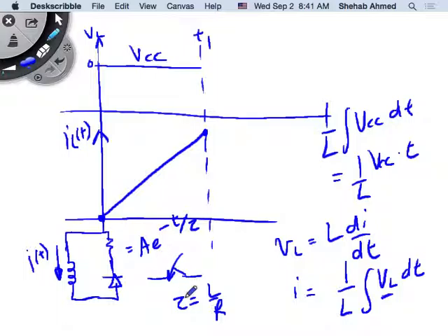So anyway, you will do a lot of that, and all these equations are in your equation sheet, so don't worry about it. And again, in this course, I don't go beyond the first order differential equation, right? So it's either going to be an RL circuit or an RC circuit, right? So that's why it's not a differential equation course. The solution to any first order system is A e to the minus T over tau. A is determined from initial conditions, right? So the idea is not to quiz you on differential equations, because it's something you studied before.